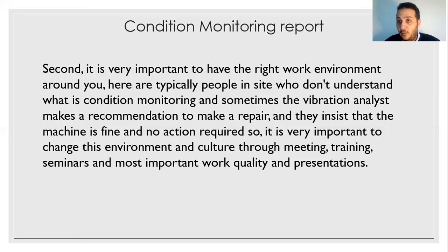When you find a bearing fault, don't just find it and forget about it. When you find a bearing fault, ask the maintenance team, when they disassemble the motor or the fan bearing, to keep the old bearing, cut it, have a look at the failure, and link this failure to what you got on your vibration spectrum. Make it a case study in your monthly or weekly meeting with the maintenance team.